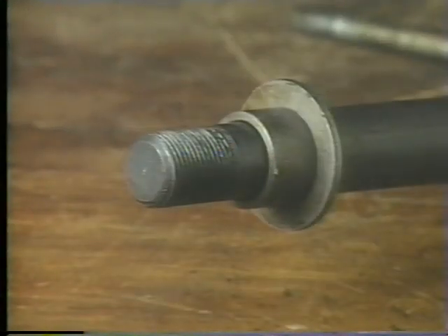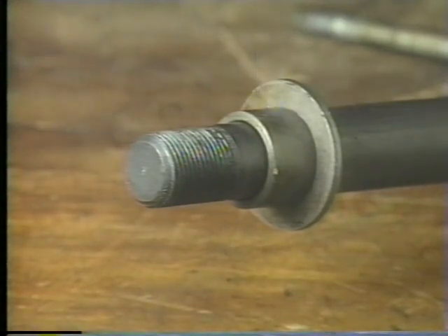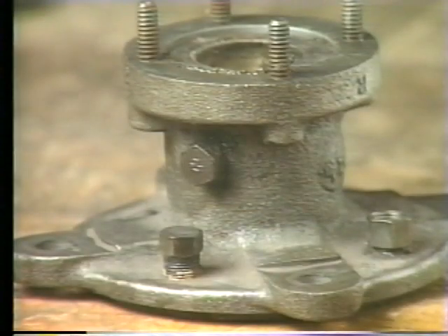Behind the second cup assembly is a spacer and washer. These last two parts of the piston assembly help to hold the piston assembly together and prevent it from coming in contact with the end cap. This end cap is designed to allow the piston rod to move through it without allowing air to escape around the rod, as we will see in a few minutes.